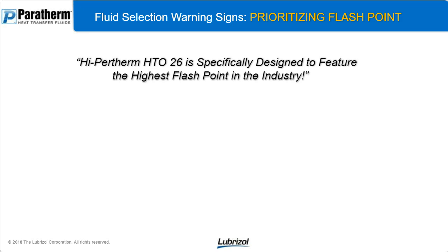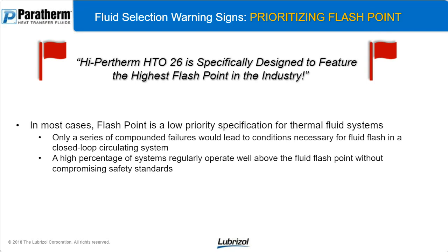And that might sound a little confusing or out of left field to those who don't really have access or haven't had this conversation before. But flashpoint doesn't really become a huge factor in a traditional industrial closed loop heat transfer system. And when you design around flashpoint, it's a red flag. In most cases, the flashpoint is a low priority.